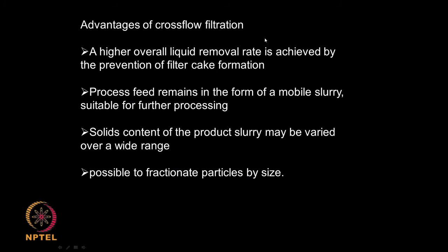Okay. So, what are the advantages of cross flow? A good liquid removal rate is achieved, because you are not allowing it to form large thick cakes, and in a dead end, thick cakes make the liquid flow less and less, and after some time the liquid flow can totally stop. And the feed always keeps moving on top. So, we can take it and do further processing, unlike a thick and dry cake, where we cannot do further processing unless you put it again in a slurry.